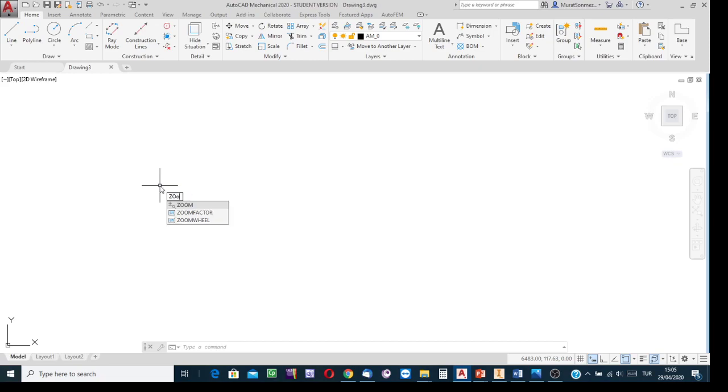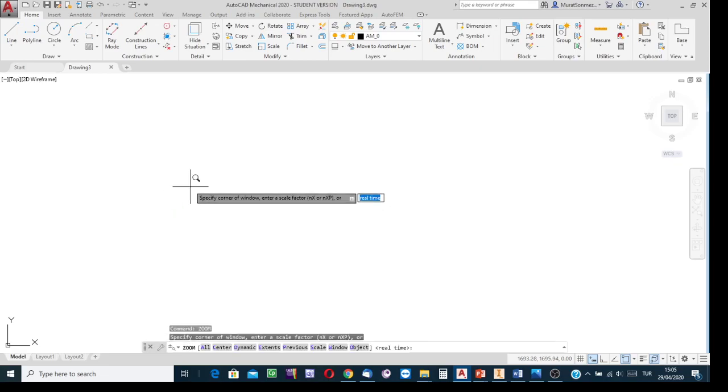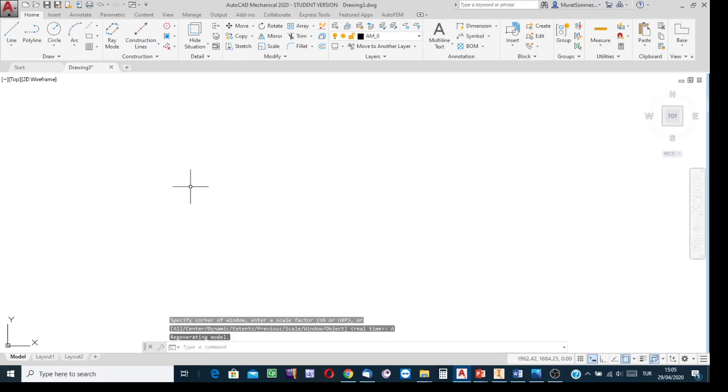Use the zoom command, select the option from the list with a click, and then drop the list of options, clicking on this little arrow, as implied, or the down direction key of the keyboard. Then from the list, select All.